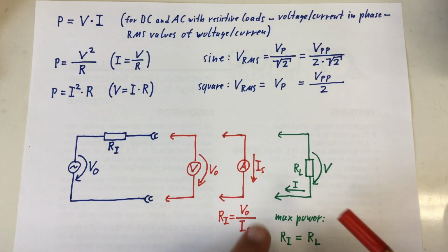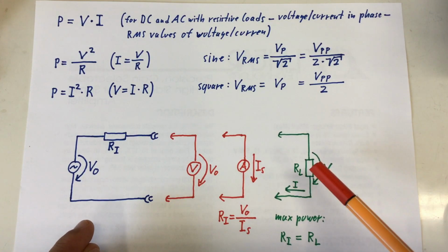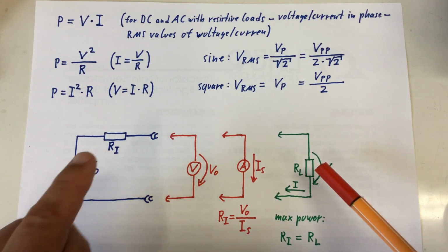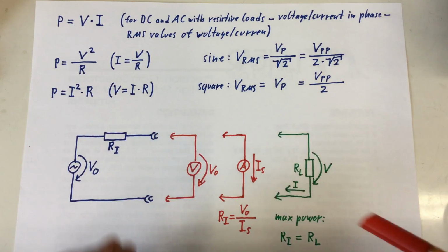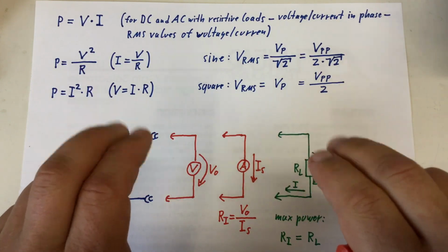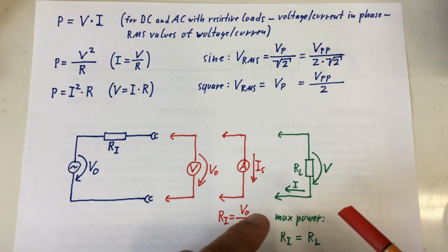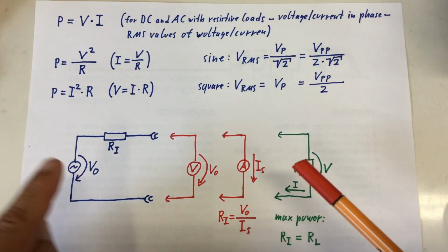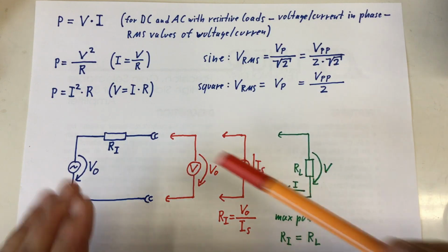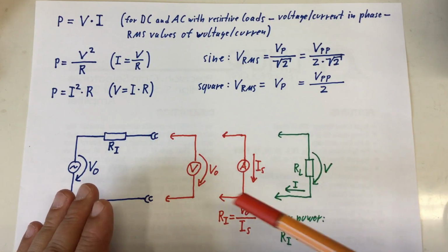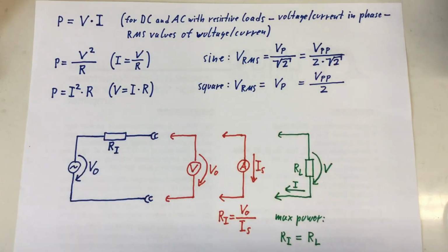And we should get the maximum power if the external load resistance is matched to the internal impedance. That's called the maximum power point, for solar cells, for example. So if these are equal, we should get the maximum power, which is also a way to determine the internal resistance of that thing without making a short circuit like in that example. Okay, let's get started with the measurements.